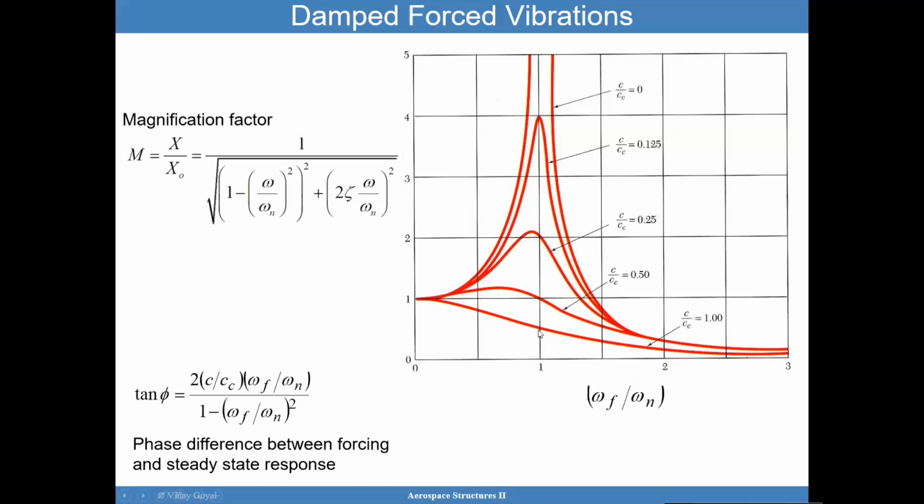And so that means that when I apply that load, if I have a lot of damping, it could cause very little motion compared to a static solution. So in some cases, if you have a heavily damped system, the static solution will be conservative compared to the solution you get when you consider a dynamic model.